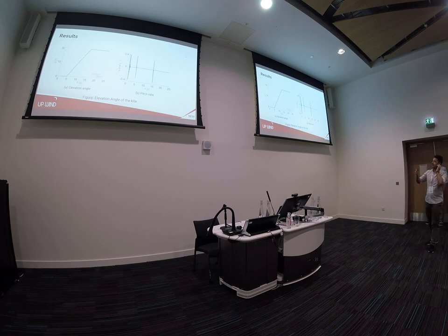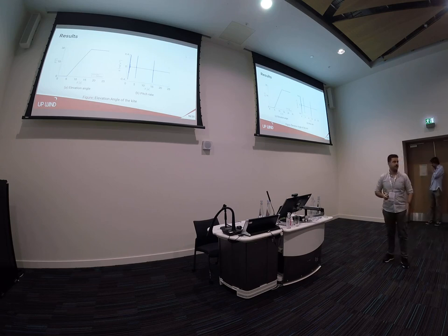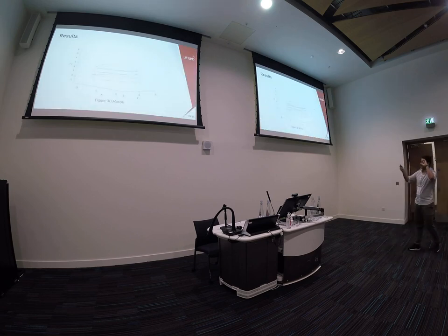And for the elevation angle, after we reach the 10 meters per second of speed, the kite starts to elevate. This is the pitch rate. We would think that it's just in the vertical plane, but as I told you, we tried to do a 3D motion, and this is our result. The kite starts to gain velocity, and at a certain point, when you reach 10 meters per second, it starts elevating until a certain desired elevation angle.